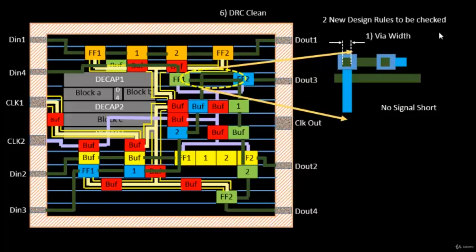So it's very important to understand what the lithography technique is, and how these numbers are extracted from the lithography experiments that we do. One of the experiments that we can share right here is that they print the square boxes that you see multiple times at varying widths, and then they come up with a width saying that this is the minimum width that can be printed by an optical light.